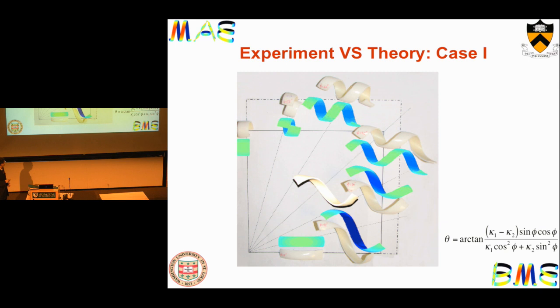And that's because the helix angle becomes 0 when either phi becomes 0 or 90 degrees. Okay? And otherwise, we get helical ribbons with varying pitch distance and changing radius of the bounding cylinder when the driving forces are anisotropic, so the pre-stretches in two directions are different.